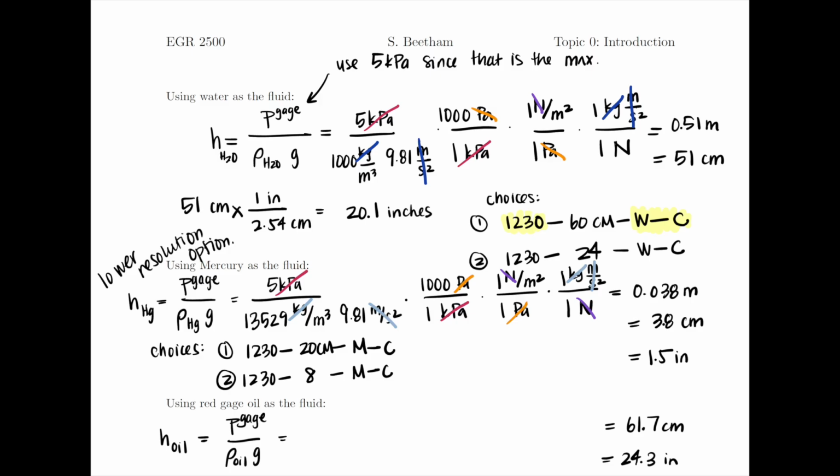So we have 2 options for this one as well. Option 1 is 1230 M for mercury, and then C for that 1/8 inch thread. And we're gonna have the same thing for the second one, but we just need to figure out that second number. Okay, so let's keep in mind the 3.8 centimeters first and go back to our chart.